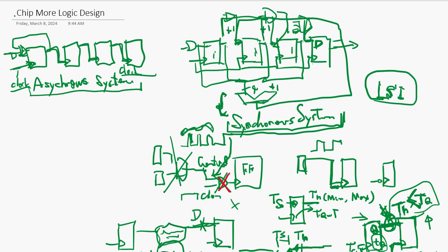On the asynchronous side, there is a logical design, like you have incoming data, and incoming data usually comes with a preamble, a regular clock, like 20 clocks, then the data area. That's the incoming signal, and your chip clock has to synchronize with this.